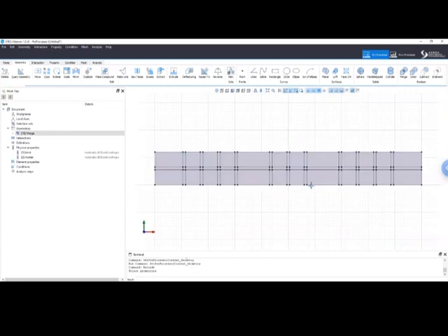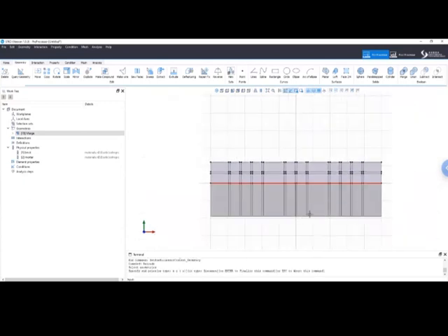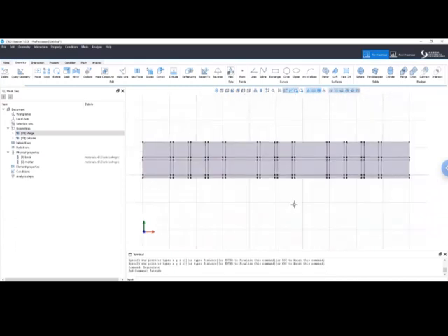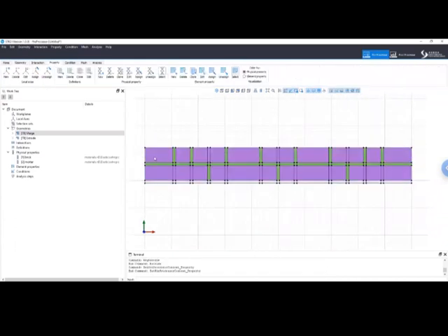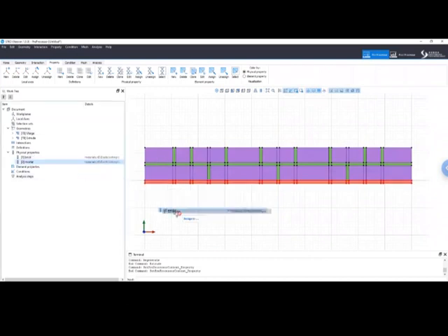Actually, what I want to do is to extrude lines into surfaces. So I unselect everything except the lines, so that I can select only these lines, right click, and then I go down of 10 millimeters. Right click, perfect.